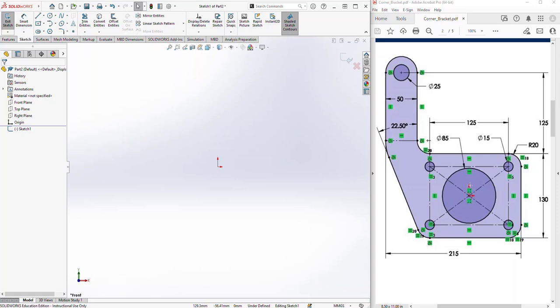And from what I see here, first thing I try to locate the origin point, and I see it here at the middle of the center circle. And I see that that center has its center point at the origin point. The circle is surrounded by this construction rectangle, which is made for reference. Again, the center point of the rectangle is placed at the origin point. And there are 4 small circles placed at the corners of the rectangle.